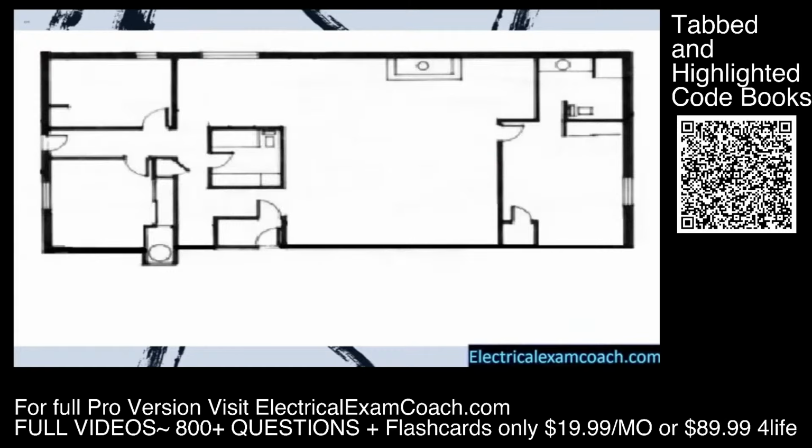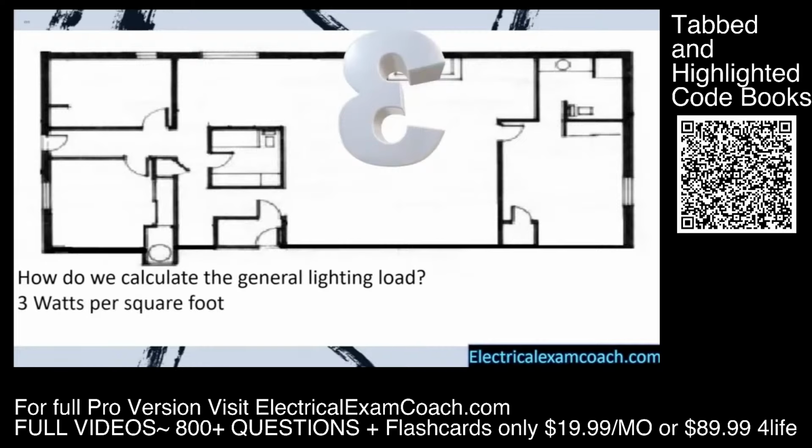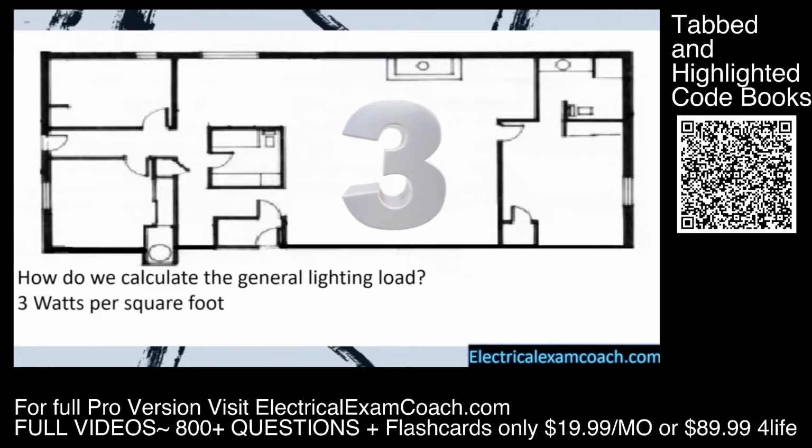The first question we have to ask is, how do we calculate the general lighting load? Are we going to calculate it per receptacle outlet, per lighting? Do we have to count them, add it all up? Thankfully, no, they've made it very simple. So we're going to calculate it at 3 watts per square foot. So for all of the general lighting and all of the general receptacles, all we have to do is take the square footage of the dwelling unit and multiply it by 3.